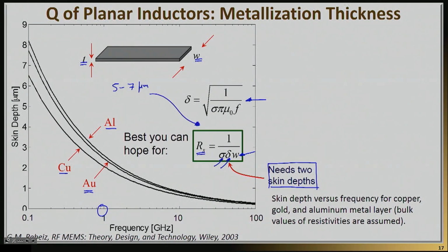And so the way we do that is by typically electroplating our metal to the thickness that you see here. But it also teaches you that once you reach 5 to 7 micrometers, any additional thickness you electroplate is actually useless. So that basically works from both sides. So if somebody tells you how thick something should be, this is a good way to explain that.